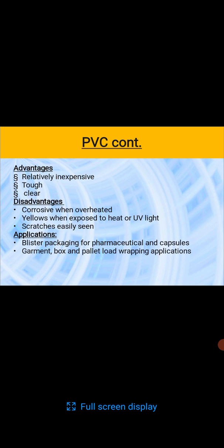Its advantages: relatively inexpensive, tough, clear. Disadvantages: corrosive when overheated, yellows when exposed to heat or UV light, and scratches are easily seen because it is very clear. Applications: blister packaging for pharmaceutical tablets and capsules, and box and pallet load wrapping applications.